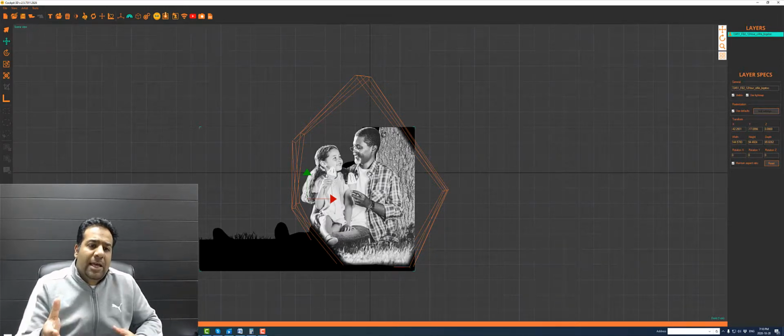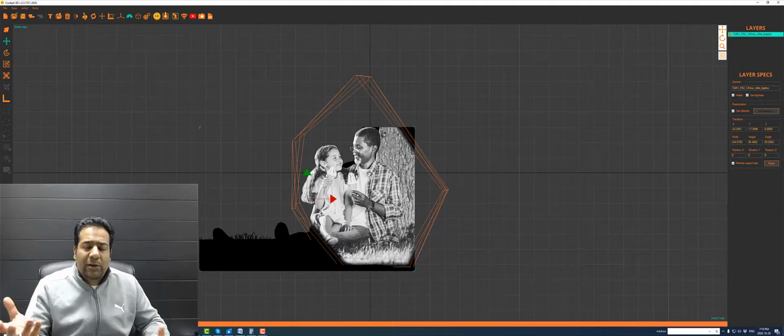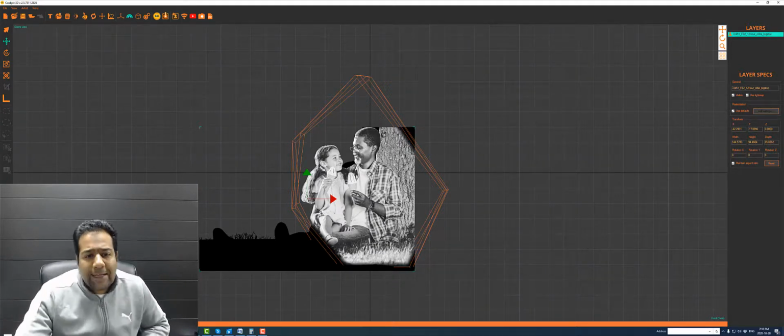And what happens is that when you save your point cloud and you load it in, your laser won't look at what the visual center is. It'll look at true center. So it'll take a look at this template and treat it like a rectangle. It'll measure it along the Y, right along the edge there, along the X. Imagine drawing a rectangle touching each of the furthest points.